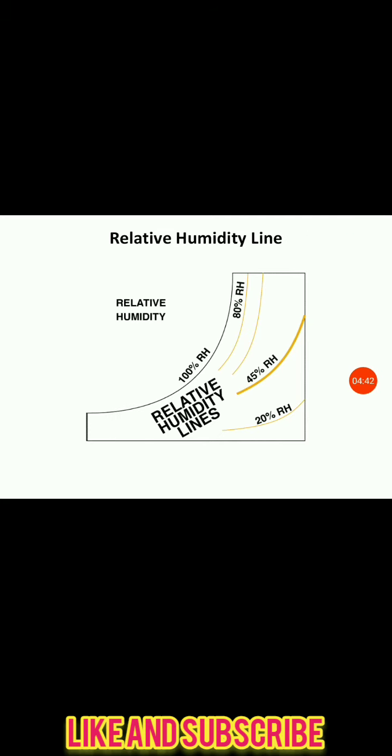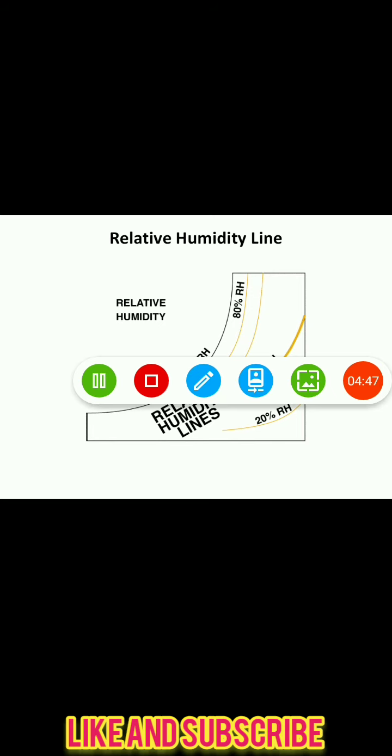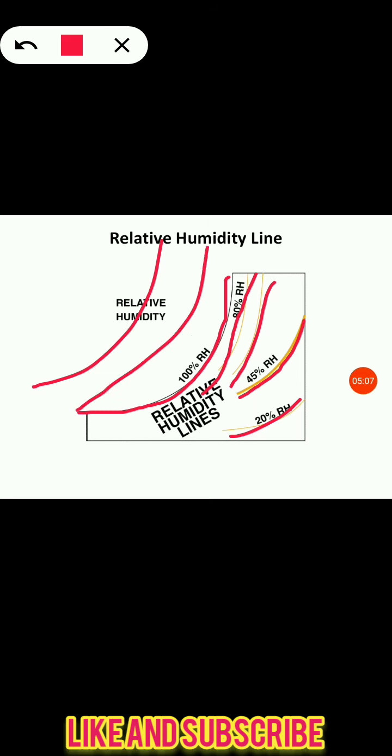Then next is the relative humidity line. As you all know, relative humidity is measured in percentage. This saturation curve is also called the 100% relative humidity line. The relative humidity lines go on decreasing as you move rightwards, from 100% down to 20% towards the end. These lines are generally curved like this, and as you move from left to right, they go on decreasing.